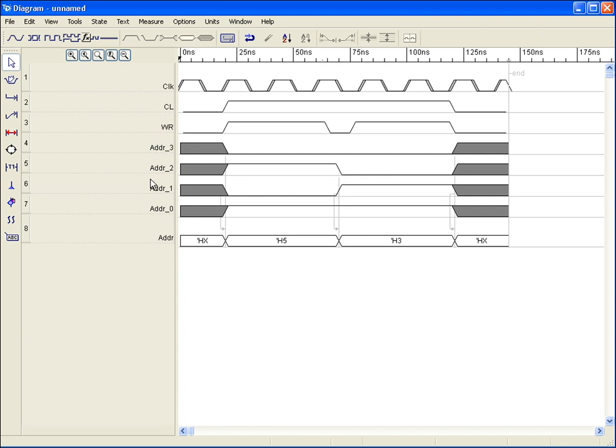Notice that the individual signal names are appended with the appropriate bit it represents, and all the state values are represented at the bit level. Also notice the virtual representation of the bus is still presented as a reference waveform. All edits to the bus must now be done on the element waveform positions, which will have their characteristics continually reflected in the virtual representation of the bus waveform.